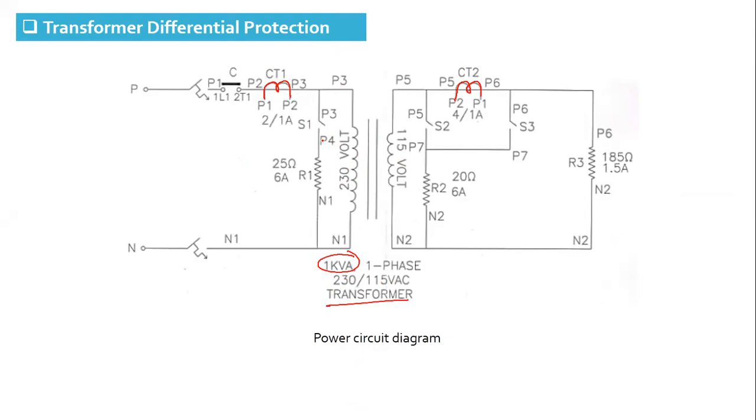And here we cannot tear up the insulation of the winding to create the fault. We cannot actually do it that way, by damaging the insulation of the winding. So what we can do, a fault is a flow of current to an undesired path. So using the switches and rheostat, we are creating, here it is the load, a parallel path which is flowing to an undesired path other than the load. So these switches S1, S2, and S3 are used to create the fault.